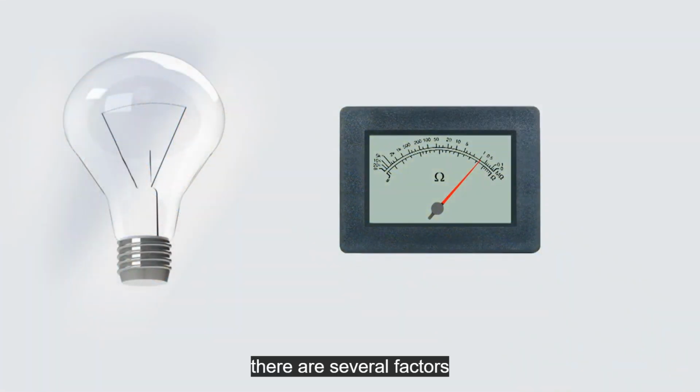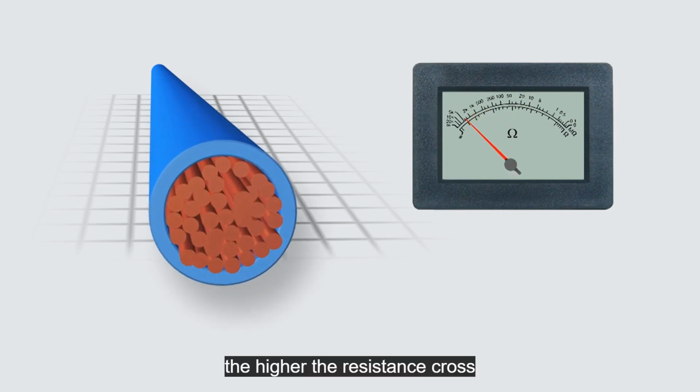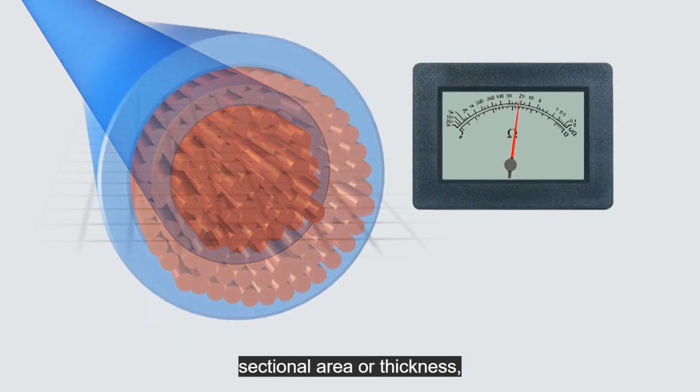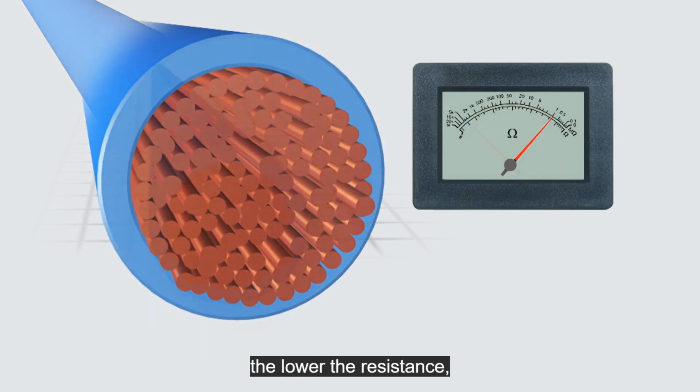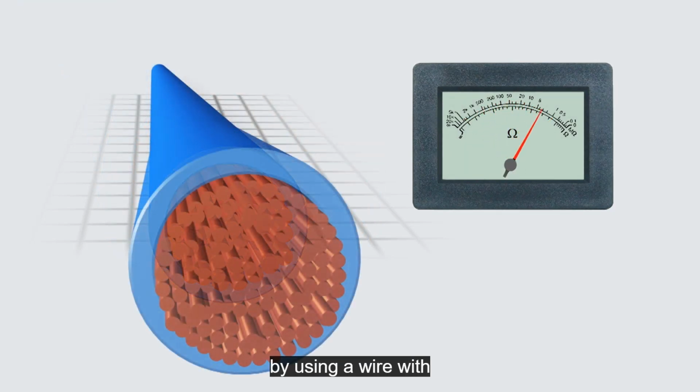There are several factors that can affect resistance. The first is material. Some will have more resistance than others. For example, a tungsten filament inside a light globe. The length of a conductor will change its resistance. The longer the conductor, the higher the resistance. Cross-sectional area also affects resistance. The greater the cross-sectional area, or thickness, the lower the resistance. The resistance of a long wire can be counteracted by using a wire with a greater cross-sectional area.